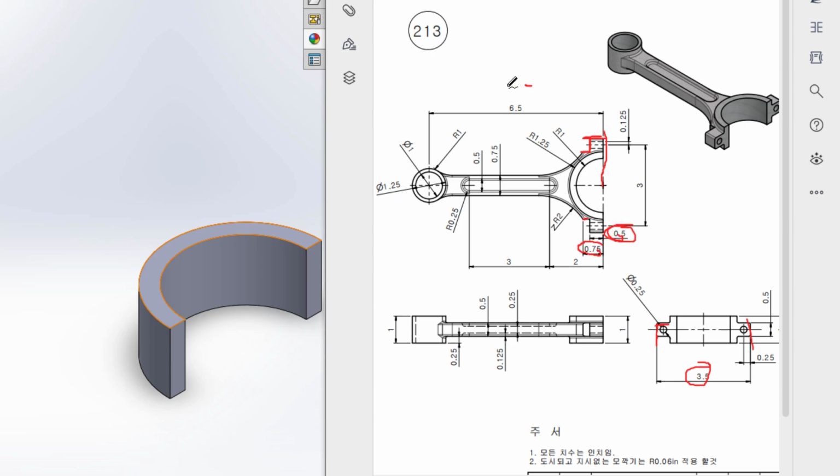And then I'll draw a circle, and this circle will have a radius of 2 unit, and from this point to this line I will make it tangent, and from this point to this circle periphery I will make it coincident. Okay, after that I will get this fillet shape here. Then we have to extrude boss it to 0.5 unit from the mid plane.